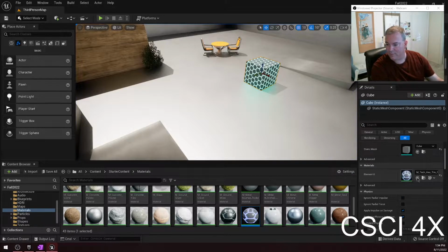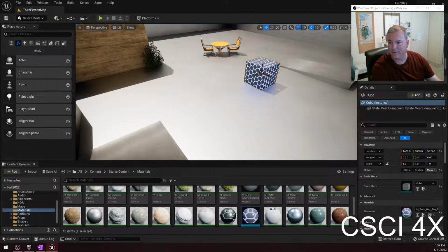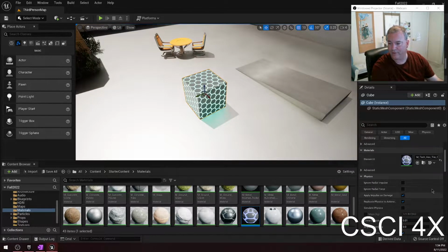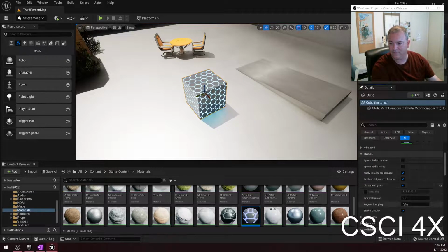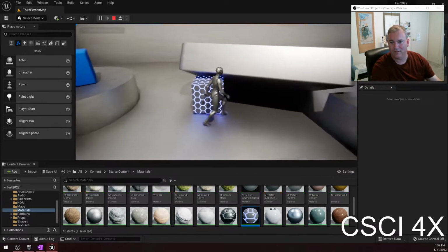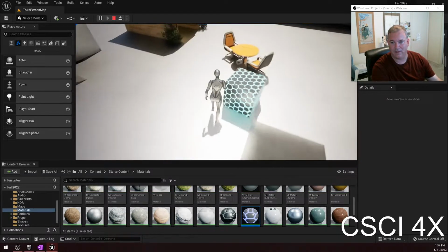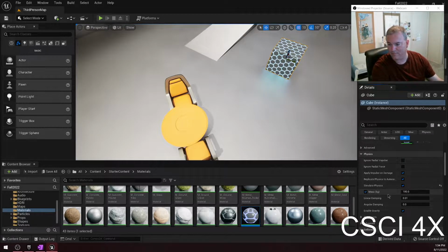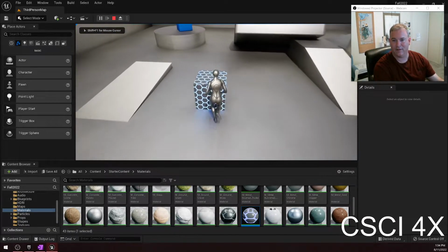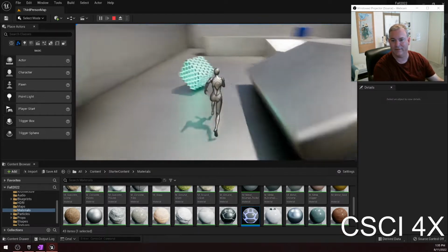They can be, note it's still not moving. And the reason for that is because we have not turned on physics yet. So if you scroll down, I've got this box here clicked on. If you scroll down a little bit, you can see that there is an option called Simulate Physics. And you can do things like set the mass of the box. Now I can come up and push it a little bit, and it's acting like a fairly heavy box because this thing is about 350 pounds right now. If I were to adjust the mass right here, I could turn it down to 10 kilograms, and it acts like a hollow little cardboard box now, right?